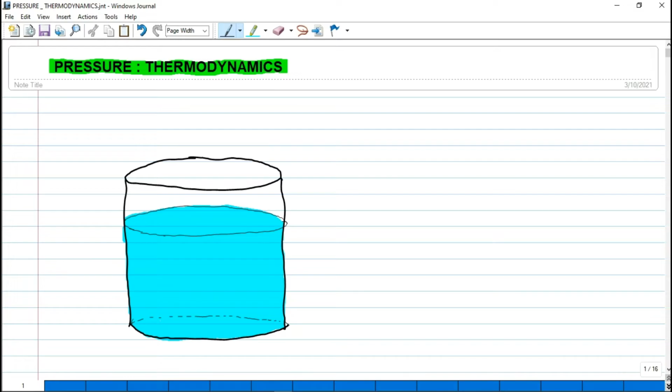So basically, the difference between pressure and stress is that we use the term pressure in thermodynamics or fluid mechanics when we are dealing with fluids, and we use stress when we are dealing with solids. So yung stress ginagamit natin yan, guys, sa strength of materials. But here, we are dealing with fluids like air, water, anything that flows. It's a fluid. We use the term pressure for the normal force exerted by that fluid per unit of area. Okay, so pressure will always be the force exerted by that fluid per unit of area. So we use the letter P when denoting pressure.